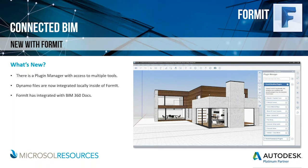The first one being the plugin manager, which we'll see in a little more detail in a bit. These are internet-based plugins and can be added and uninstalled as needed. So to the point of FormIt acting as a pre-flight tool for bringing SketchUp into Revit, the plugin manager allows you to do a couple of things. There are a couple of tools down here: validate and clean tools for SketchUp, or even for Entourage information, where you can basically fix any issues and get them more BIM ready. So you can use this panel and these out-of-the-box plugins for that type of stuff.